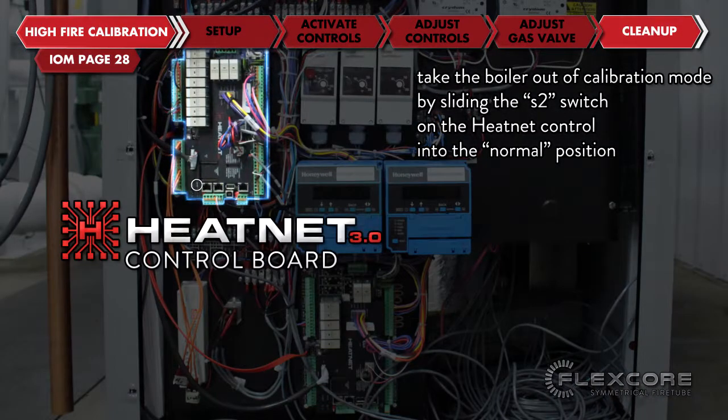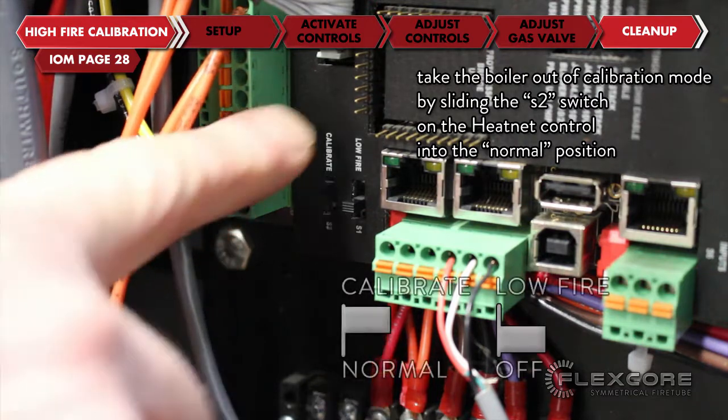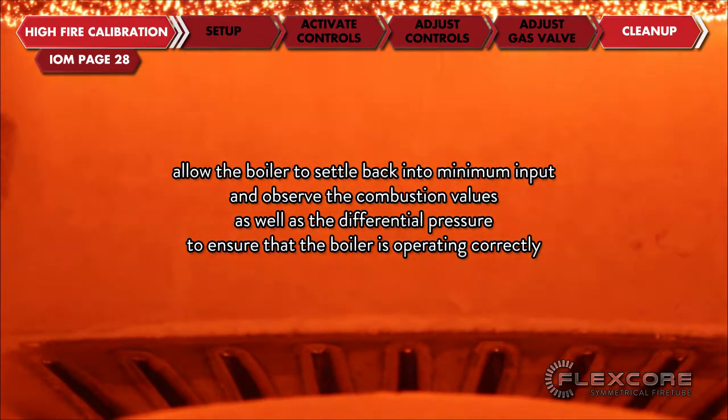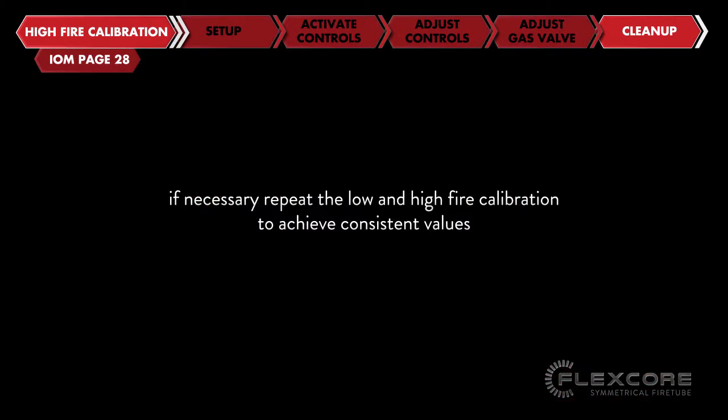Take the boiler out of calibration mode by sliding the S2 switch on the heat net control into the normal position. Allow the boiler to settle back into minimum input and observe the combustion values as well as the differential pressure to ensure that the boiler is operating correctly. If necessary, repeat the low and high fire calibration to achieve consistent values.